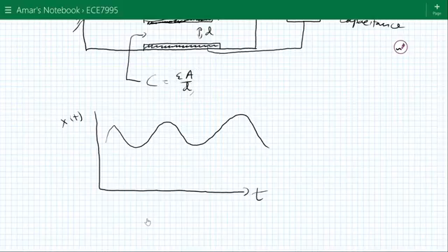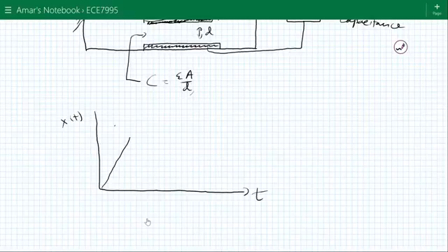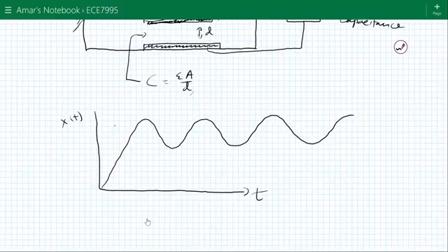In an underdamped system, from the moment you tap the beam, the beam will start to resonate at its resonant frequency. So it'll just basically vibrate. In a perfectly underdamped system, where there's no damping at all, that damping coefficient B that we looked at previously, if that doesn't exist, this thing will vibrate indefinitely. It'll continue forever. So this is an example of an underdamped system.